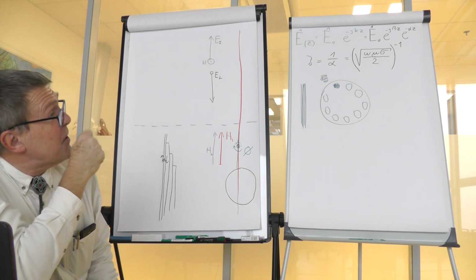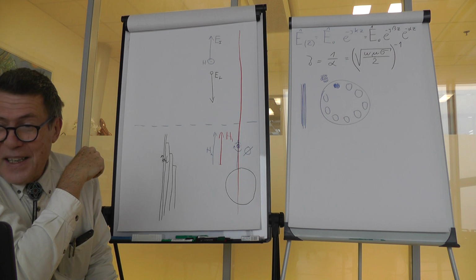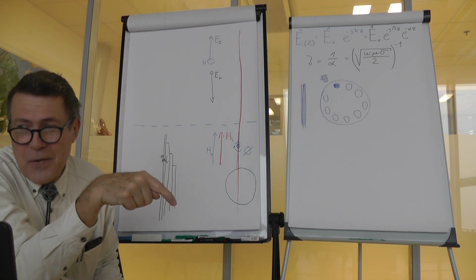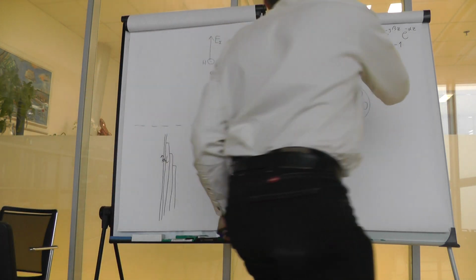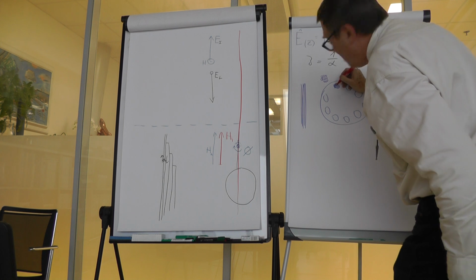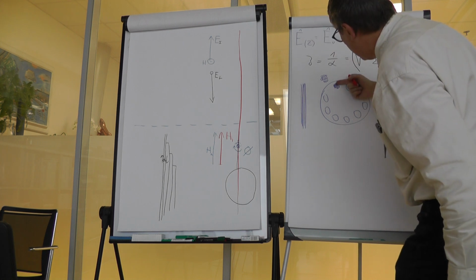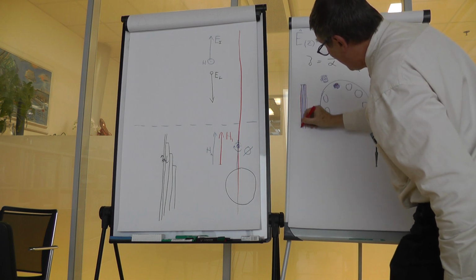Okay, this is the first solution, but then as the position of those conductors differs against the center of the system, they would have different induced voltages. I mean, if this rotates, a conductor on the outer side would move faster than a conductor here, which would result in a current flowing in between those two conductors, just in the same hole.